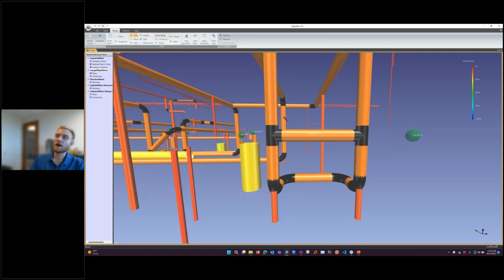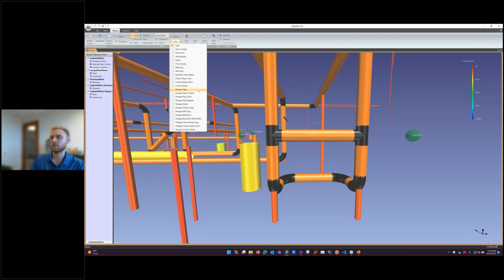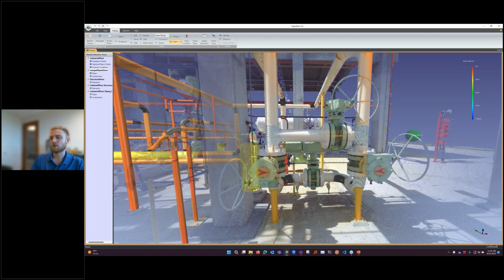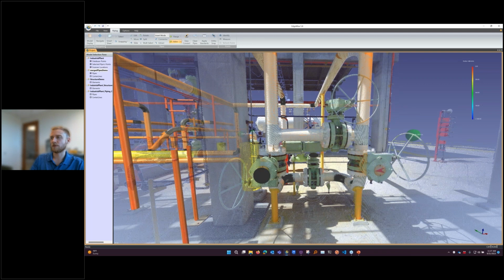And then we do have valves. These are spec driven. So it's a pretty limited list, but we can add in some basic valves here, and these will also translate into the piping run when we go. And these are more for placeholders than really anything else, like for the level of detail for positioning, anything like that, but they're great to have, and they will come in as sub-equipment when we actually export this to E3D.